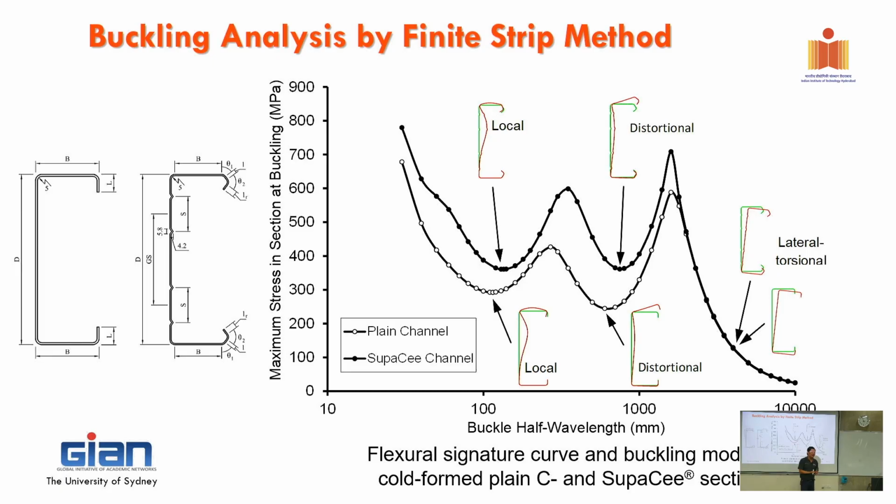Right. So as engineers now, we play around with optimization of the cross section. What is the best? Right. We don't want to make something very stiff on the lip, but then this one is plain, is no good. Because you have this one, but you don't have this one. So it just fails in local buckling. It doesn't matter that you make the lip a lot stiffer. Or the other way around, if you make it very strong in the web, and then something in here. So it's a balancing problem, okay?